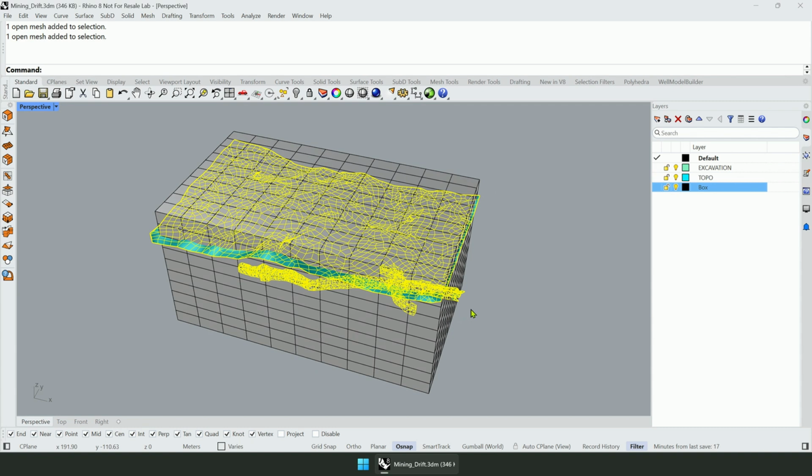So let me select the interior meshes, and I use the mesh split command. There are different ways to trim pieces, but we'll use mesh split just to illustrate that there's an option to create n-gons. So by default, splitting meshes will create n-gons. You can set this option to no, then all the intersecting faces will be triangulated.